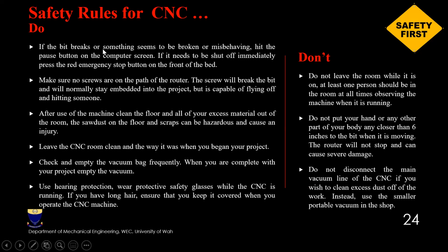The other ones: if the bit breaks or something seems to be broken or misbehaving, hit the pause button on the computer screen. If it needs to be shut off immediately, press the red emergency stop button on the front of the bed as well. For emergency stop, make sure no screws are on the path of the router. The screws will break the bit and will normally stay embedded into the project, but are capable of flying off and hitting someone. And basically, sometimes in projects or in parts, there are screws embedded. You have to ensure the safety of those screws while machining as well.